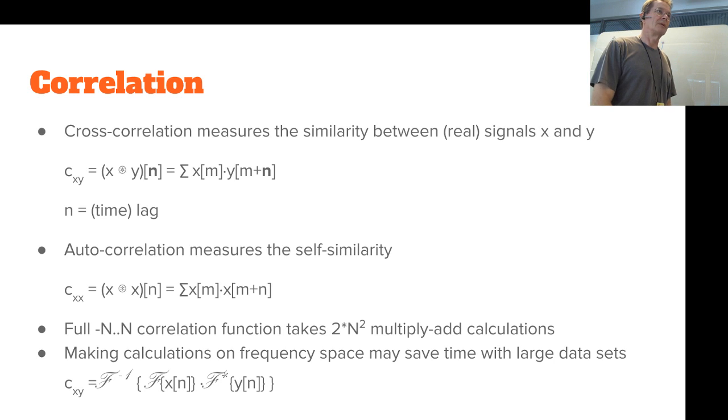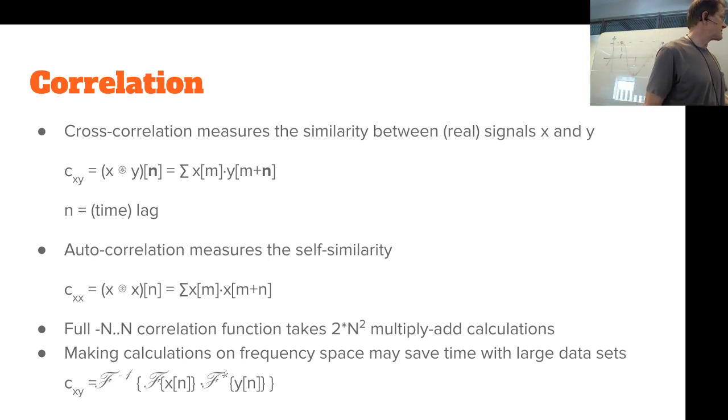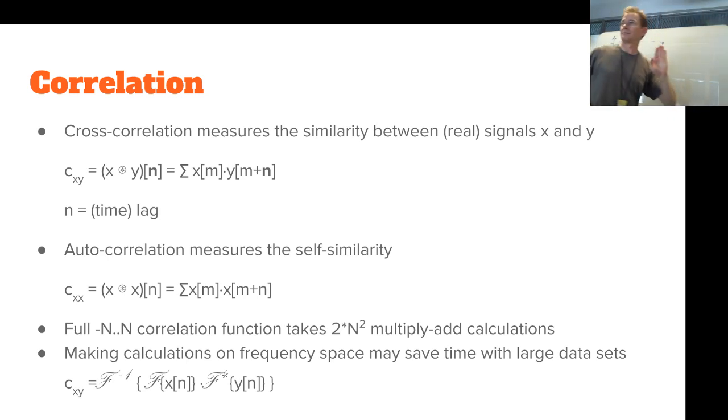If you want to know more about radars, go to Otaniemi. They have really nice radar technology classes there. But after all, the signal analysis for radar kind of systems is basically just correlation analysis. You just sample fast enough and then collect the data and do autocorrelation, which has both the sent signal and the return signal the same. The only small problem is to have enough dynamic range to fit those in the same system.